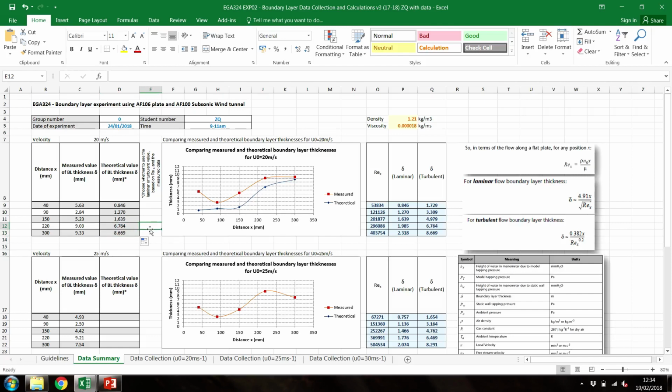That's starting to look like it matches a little bit better, doesn't it? What I've done is use the laminar boundary layer theoretical values at the start, which is much closer to what actually happens in the experiment, and then at some point around 200,000-300,000 Reynolds number, it transitions into turbulent behavior.